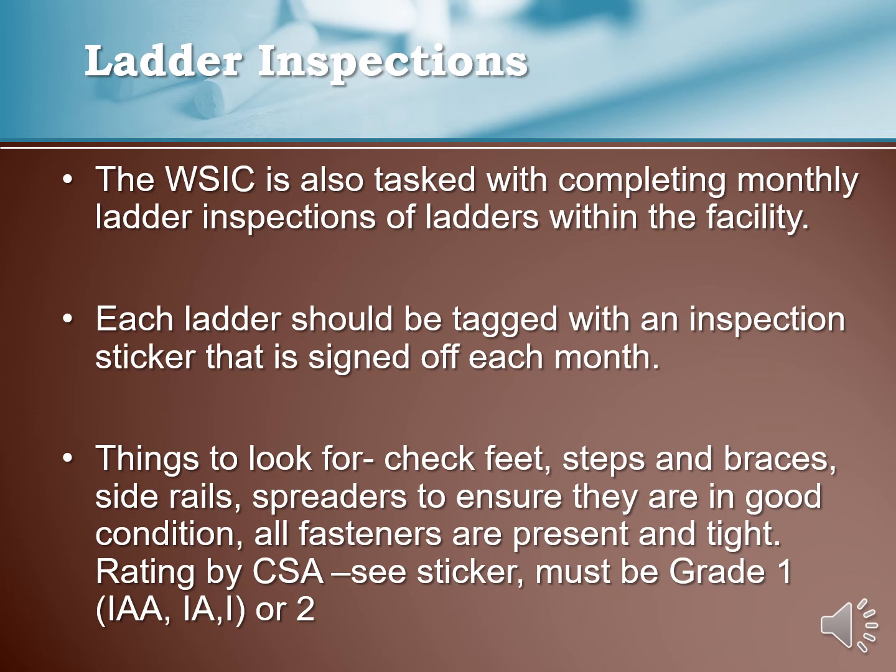There should be rubber feet on the bottom of the ladder. All fasteners must be present and tight, and there must be a sticker on the ladder to indicate that it has been rated by CSA as a grade 1, 1A, 1AA, or 2.